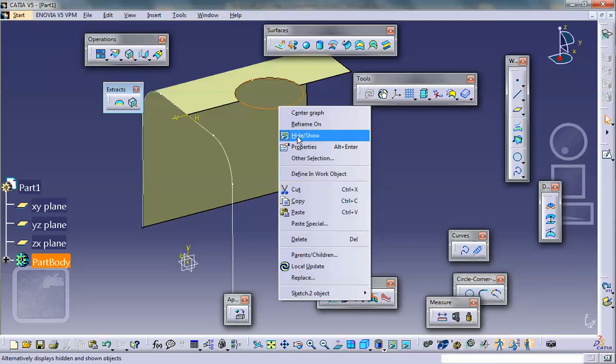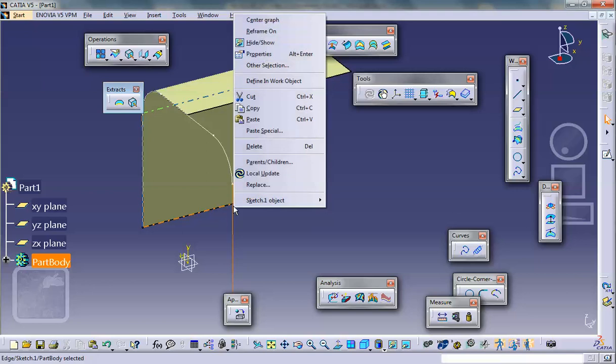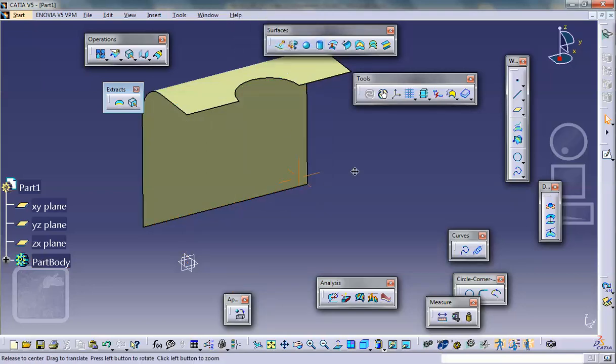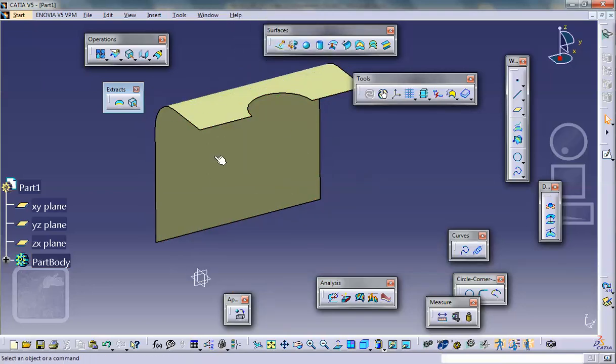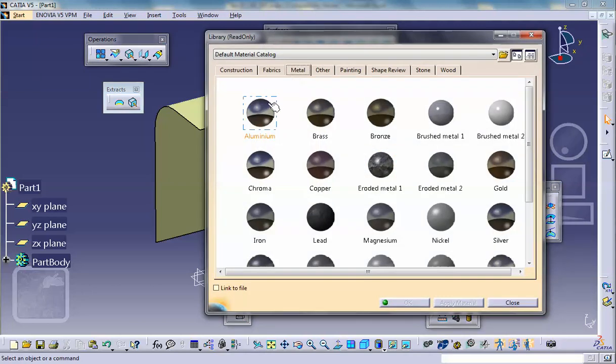We can hide these things. These geometric things, they don't participate in the FEA. So I'm going to hide that, and I'm going to hide this. Now, there's no reason to join, because the way it's done, it's all a single sheet metal. These sides talk to each other. Okay. And let's apply material to it. So where is apply material? And let's make it out of metal, aluminum on that part.